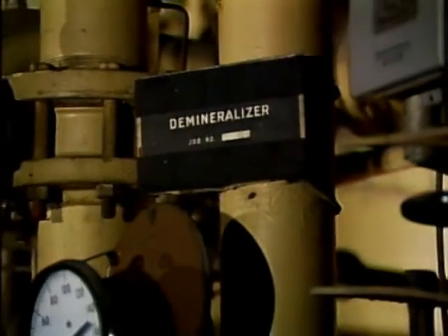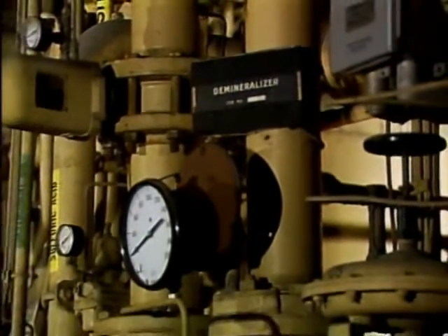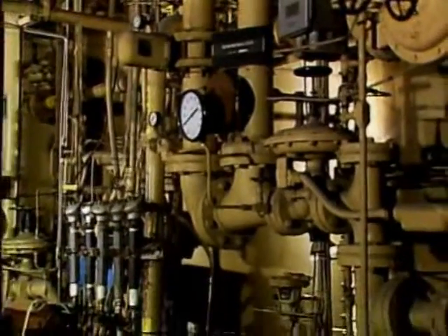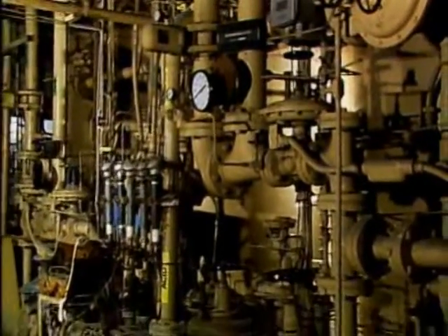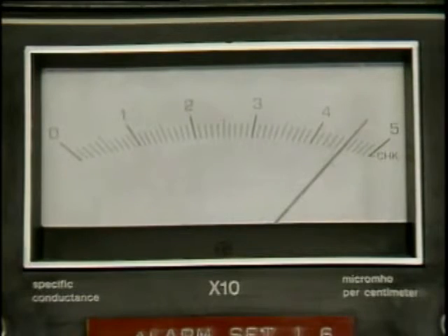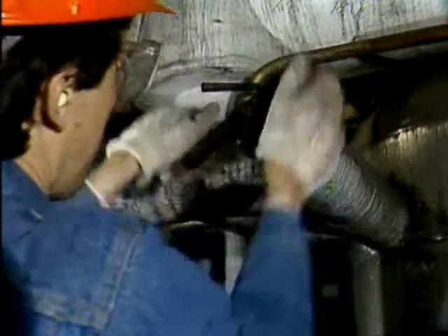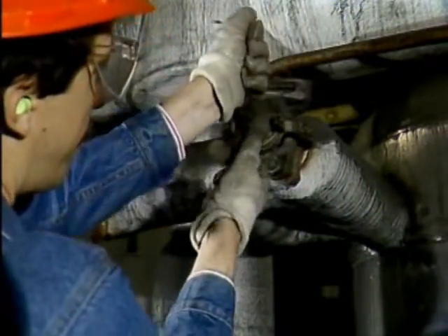But regardless of the scale that's used, conductivity measurements can serve a number of purposes in industry. For example, they're commonly used to check for dissolved solids in boiler water, which can cause scale buildup in boiler tubes. Dissolved solids increase the water's conductivity. If conductivity measurements indicate that the water has a high level of dissolved solids, operating personnel can change treatment procedures to prevent scaling in the boiler.